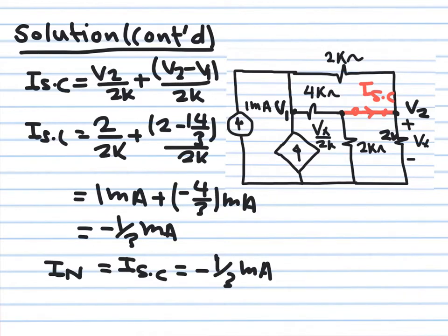Now the second part we would like to do, I'm gonna get rid of this short circuit and put an external source here. I will make this one open circuit because this is the only independent source I have. And so the circuit will simplify a lot. I have only one source here, and I would like to get the ratio between this 1 volt source, which I'm going to be getting, and the current drawn from it, because this will give me the Norton resistance.